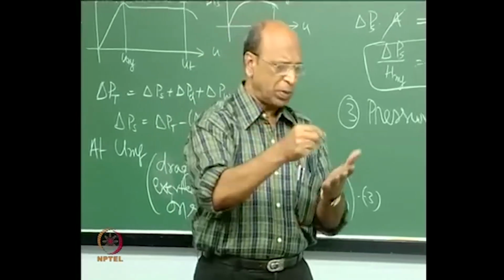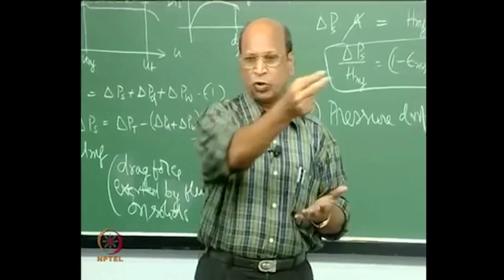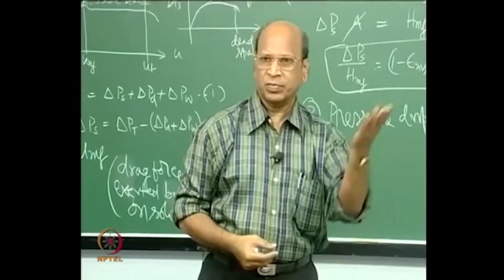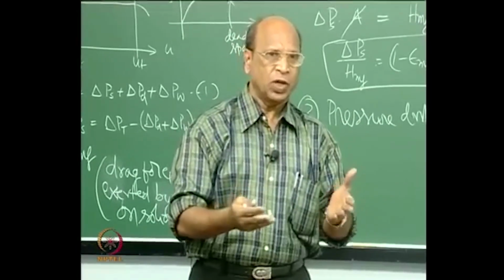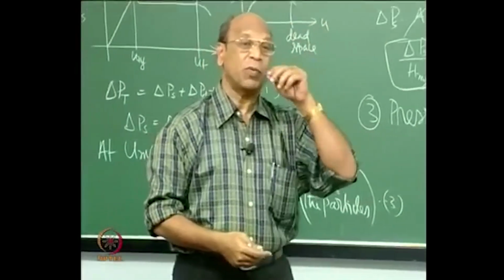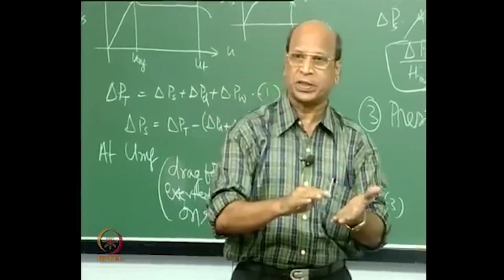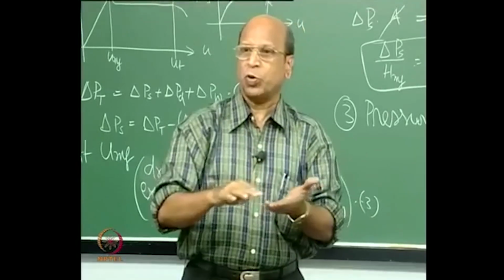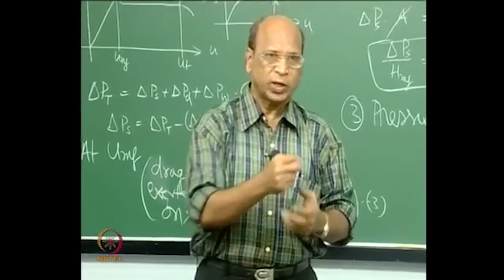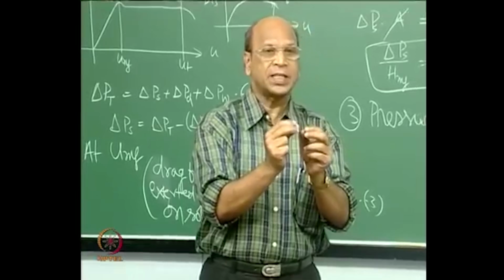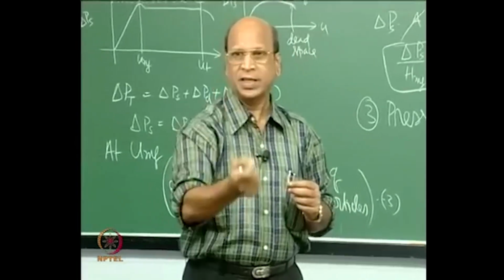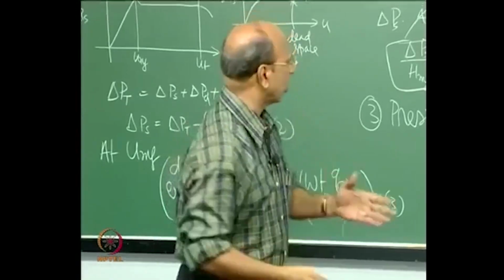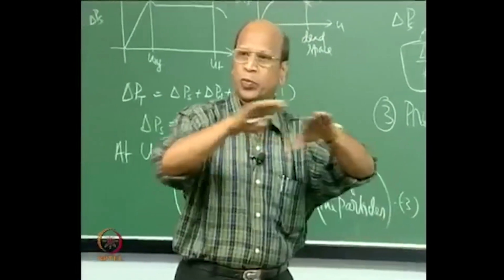I mean, what you have seen may be 1 inch, very small one, what you have done in the chemistry laboratory. So, that is what I am telling you. That also can be used, that is very widely used, because we need some kind of pressure drop across the distributor for fluidization. That only gives sufficient energy, because that will increase the flow rate, velocity. And what we are calling minimum fluidization velocity is the superficial velocity only.